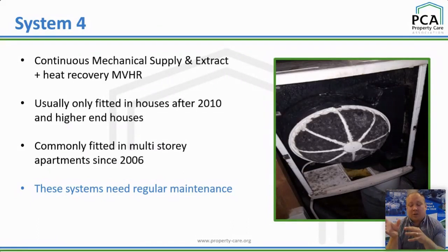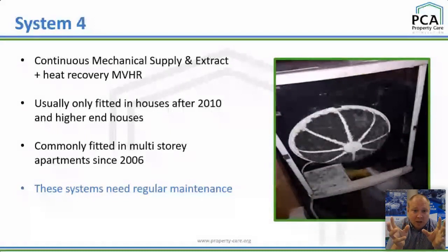So when they do go in, they go into new builds, and they go in relatively early in the construction phase. If you can imagine, there's ducting that will run through joists and that sort of thing. So normally they're going in pretty early, and then the guy will put it in, commission it, and then leave site. After that, you'll have your plasterers or whoever it may be, your dirty trades, who will make a huge amount of dust. The extractor unit is already running because the electrician's done his bit and left site. And by the time the occupants are in, the filters are clogged, the whole thing's knackered.